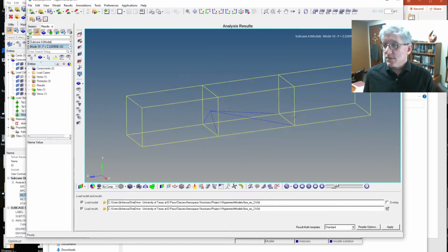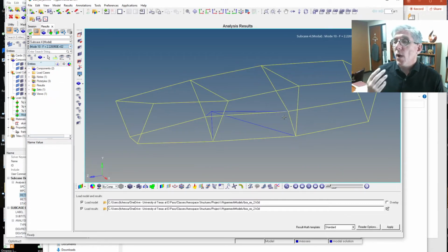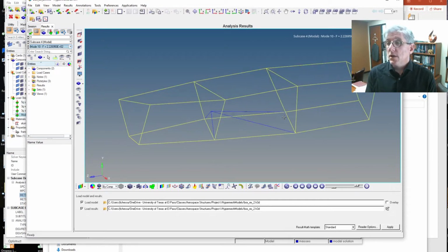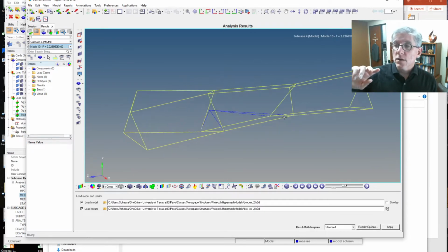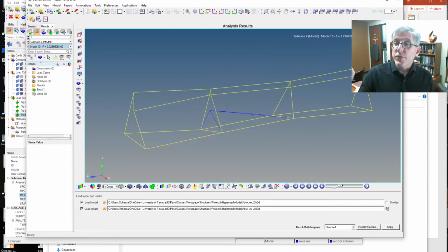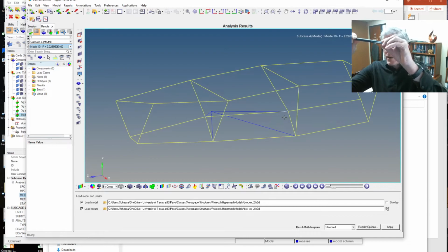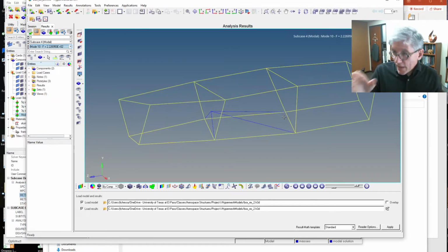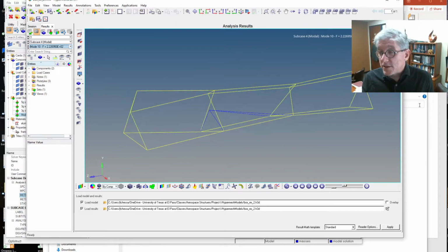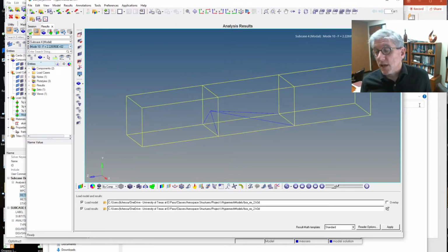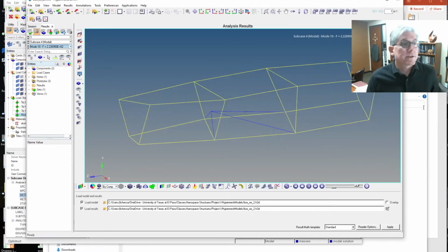Now, you can't see stresses and you can't see displacements because this is a free vibration problem. So the only way you could know how much it's vibrating or deforming and then the resultant stresses is to say, we have some initial conditions. Like, we initially move these points, we displace the end and let it ring or something like that, right? Here's the structure, and we pull it down a little bit and let it vibrate. You know what I mean? That's a vibration problem with an initial condition. Still a free vibration problem. But if we were to set that up, it's a different type of analysis. You would see stresses and displacements, but only because we've defined that initial condition. In this analysis, we have not defined that initial condition, okay?